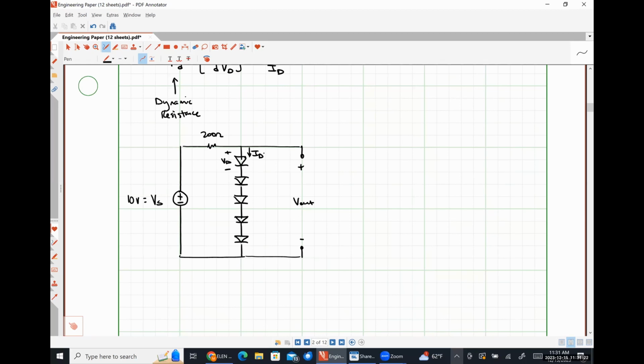And we perturbed our source voltage by plus or minus 10%. So let's say here that VS is 10 volts plus or minus 1 volt, where this bit right here is our Q point level, and this bit right here is our perturbation. IS was given to be 10 times 10 to the negative 15 amps.